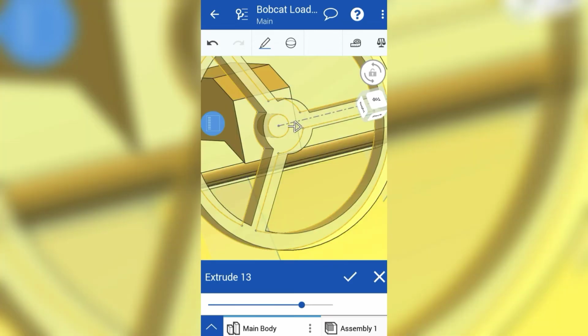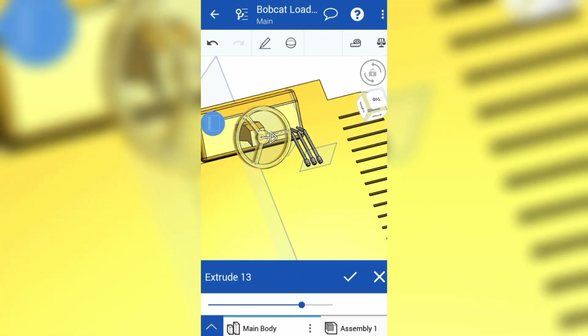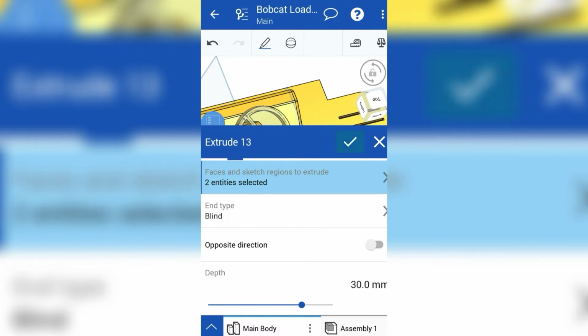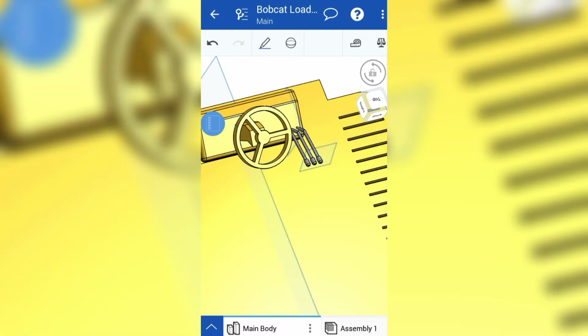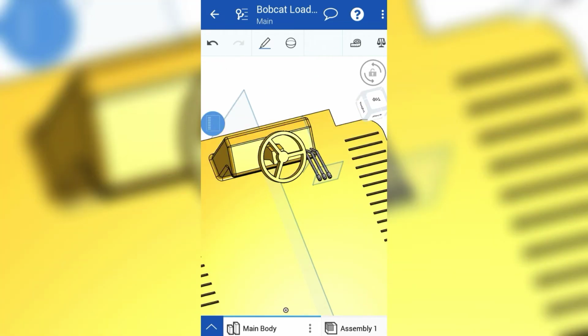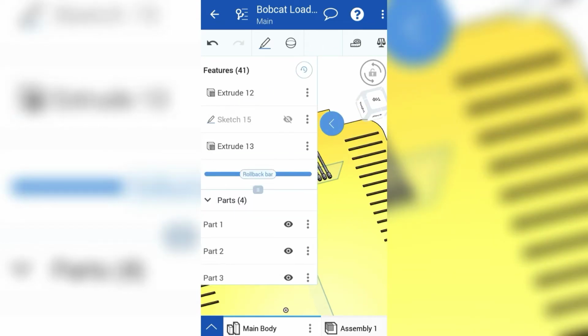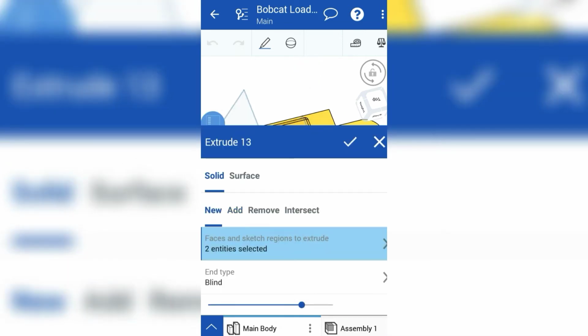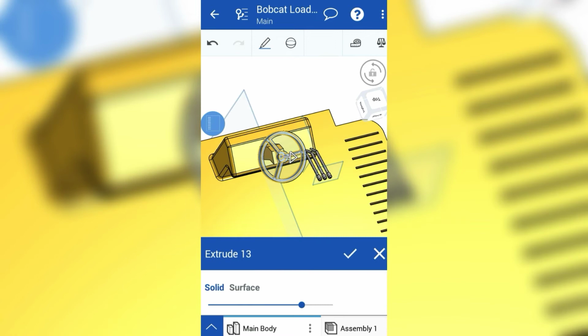extruded. We want it to be a new extrusion since its color should be different. Give the depth up to 30 millimeter and in blind direction. The appearance was not given, so before that let's edit it to new.